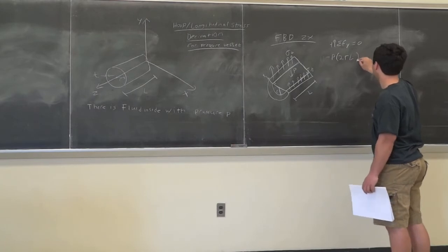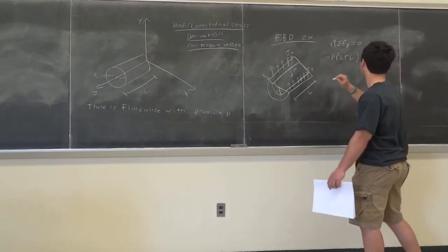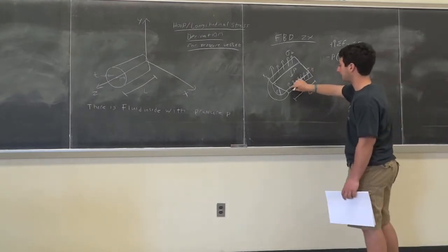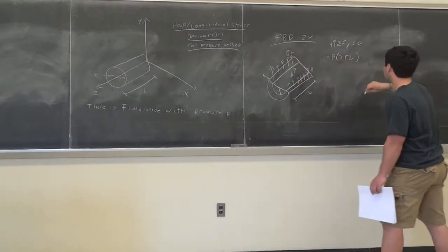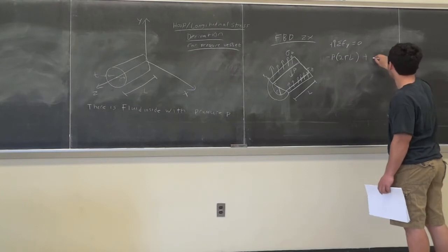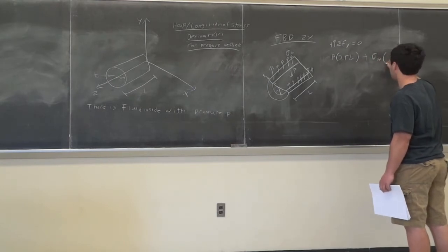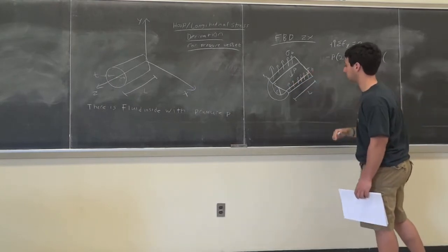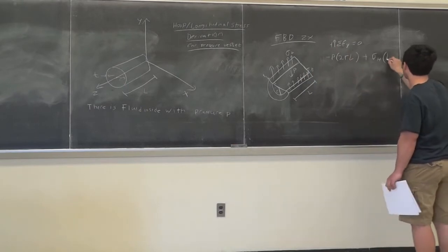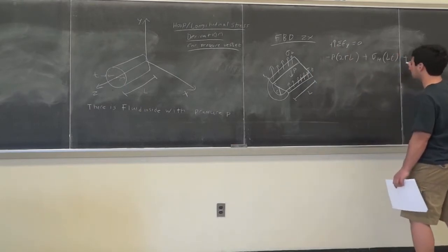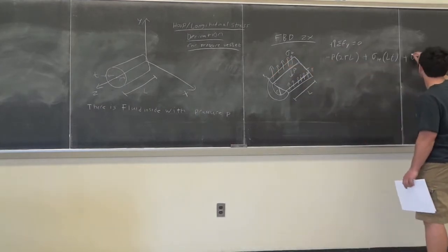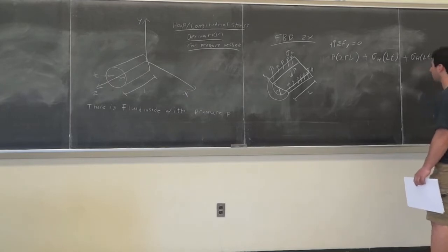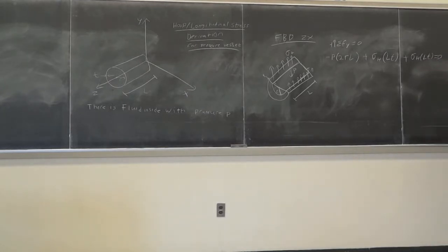That's the area, right? And sigma h is pointing upwards, and it's acting over two areas. There's a rectangle here, and there's a rectangle here, right? So you have plus sigma h times this corresponding area, which is just L times T, plus sigma h times L times T. Okay, all right, so that's your force balance, right?